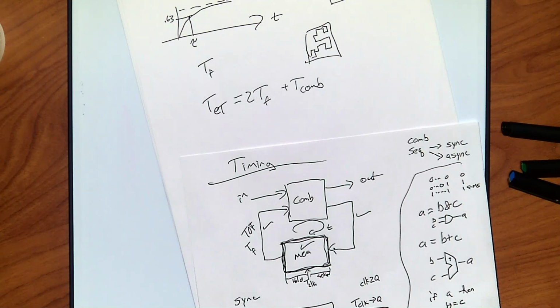Right now, you don't have to perfectly see, you just have to understand there is a trade-off and where the time is. So, generally speaking, we make a rule: the larger the combinational logic, the slower. Or, always, no. But generally, if I'm reducing latency, it will probably become bigger to allow me to do it, because I have to pre-calculate stuff and do specialty things to get it.